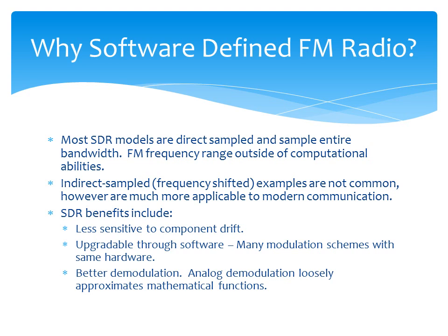So what's the big deal with software-defined FM radio? Well, software-defined radio has a number of benefits over traditional analog radio technology. It's less sensitive to component drift, which means your capacitors changing value over time and such. It's upgradable through software, which means potentially one set of hardware can demodulate many different types of signals with a simple software upgrade. And you have the ability to perform better demodulation since you can actually use mathematical functions inside a DSP instead of analog approximations that you would with traditional radio.